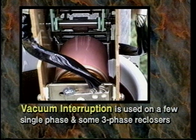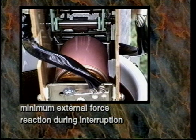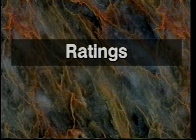Vacuum interruption is used on a few single-phase reclosers and some three-phase reclosers. It has the advantages of lower maintenance frequency and minimum external force reaction during interruption. Ratings.